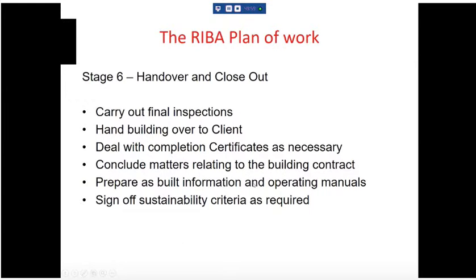We also have to make sure that it all adheres to the regulations, so all these fire exit signs are up, etc. And you need what's called as-built information. So you will have done your drawings, all the plans are there, but if things started changing for all sorts of reasons as the building started getting built, well then you have to update your drawings so that the client has a set of drawings which are exactly the same as the building that's been built. And finally, if you're doing sustainability criteria, there'll be a whole raft of key performance indicators that need to be tested to make sure that the building does indeed comply with that excellent rating and there's not a big fudge going on.